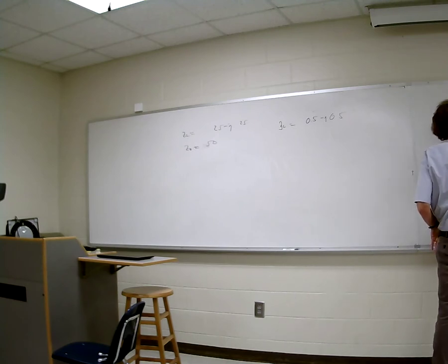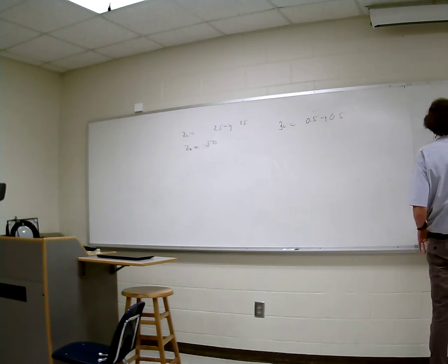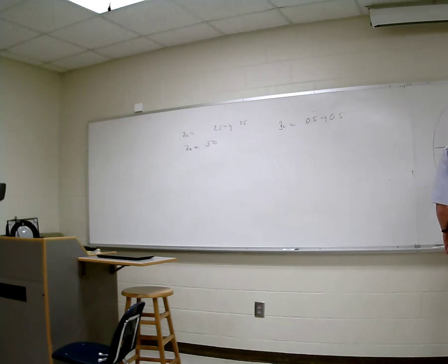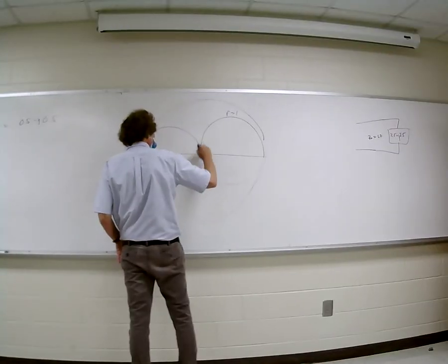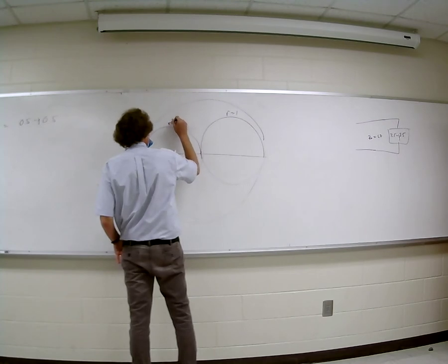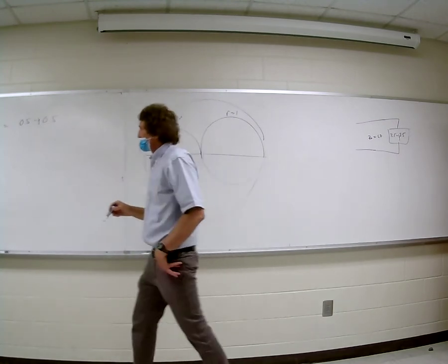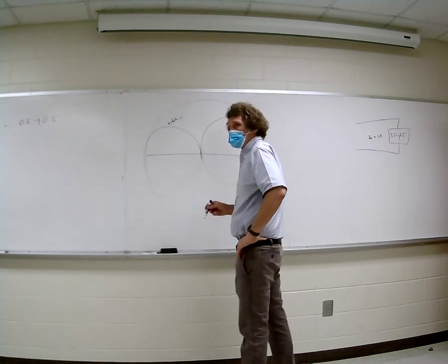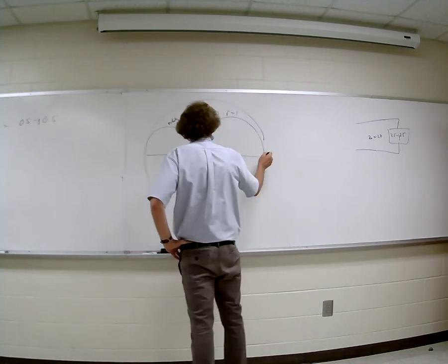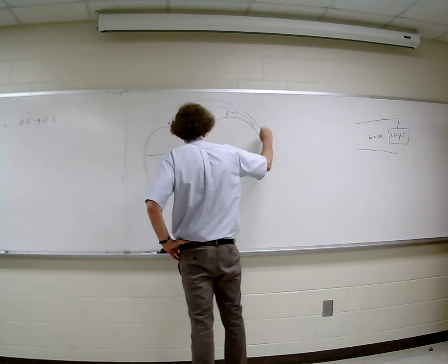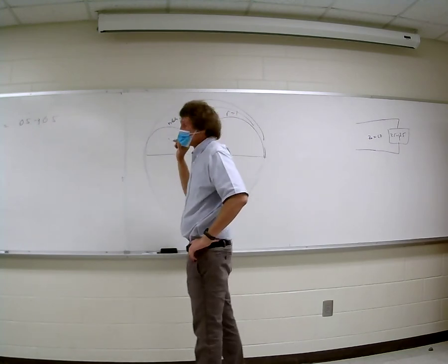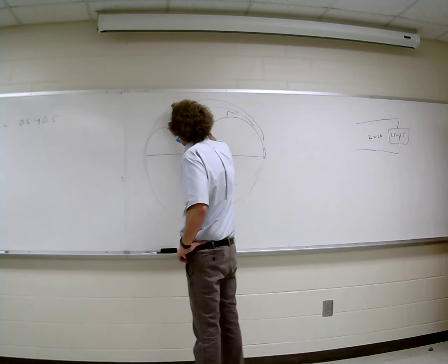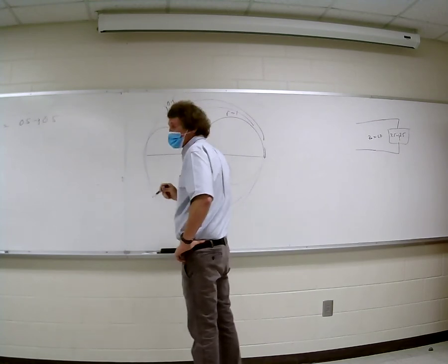Well, I'm going to draw, you have Smith charts, rotated Smith charts. I'm going to draw one. And here's my rotated one. All right, so when I plot this point, 0.5 minus J 0.5, where is it? Well, I know the 0.5 circle is here, something like that, correct, class? Just take a look. Now, where is J 0.5? Somewhere out here, right? Do you agree with me?